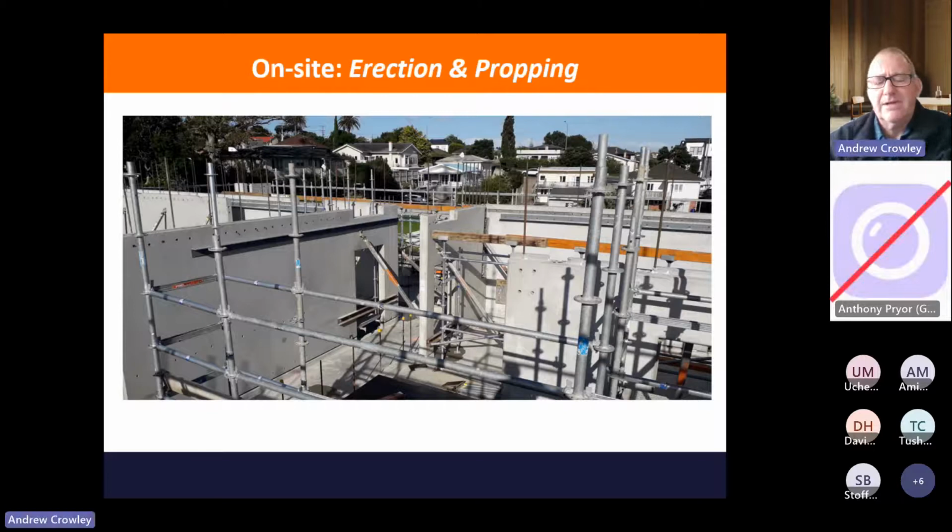Many of the props can get in the way of you moving around the site, so it's quite important to plan where you put the props. It's doubly important when these internal panels are either 2 stories or maybe even 3 stories, that you've got nowhere to bring your prop back down to, and it will interfere with the next level.